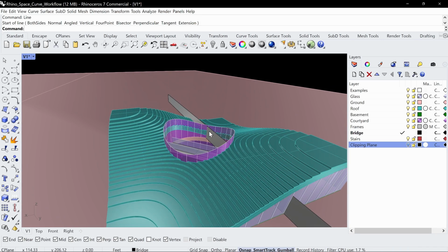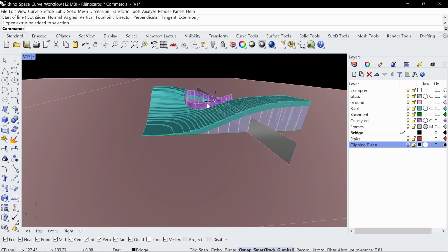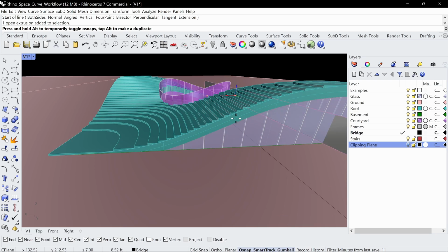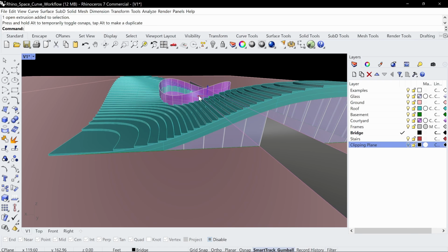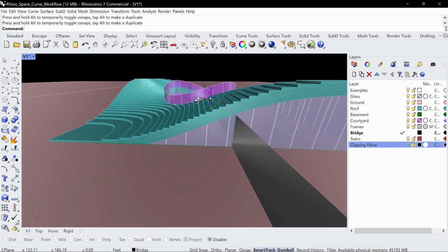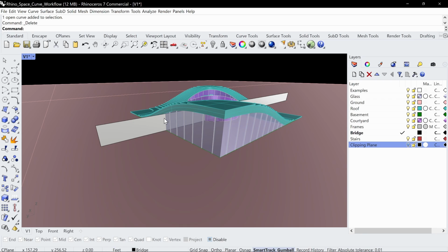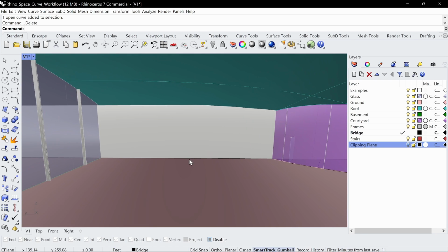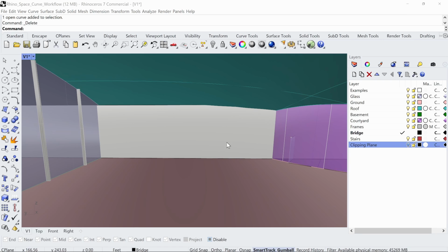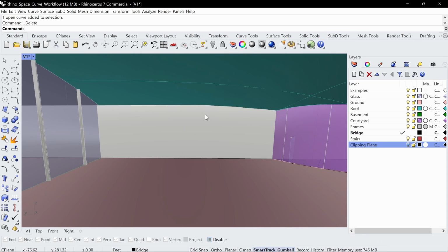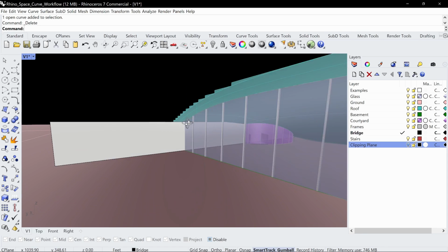And I'm just going to eyeball it. It doesn't have to be super accurate. So I'm just going to drag it until it looks like it's around 8 feet. I can turn off my O snap as well, just so I can move around easier. So let's go like this. This isn't bad. So the reason why I'm placing this surface here at 8 feet is because I want to get a good sense of where the 8-foot limit is for the ceiling, so that if someone in real life was going to stand here, right? If someone was going to stand here, you would have a good sense of scale, right? Of not being too shallow of a ceiling height and not being too tall at the same time. So I'm using 8 foot as the threshold.